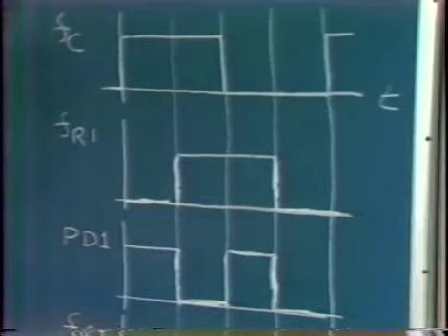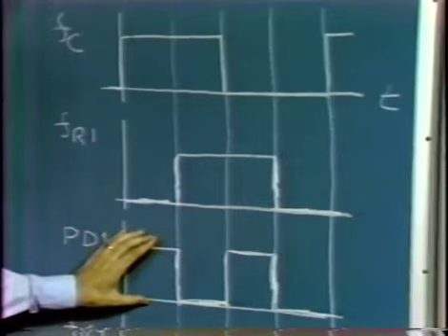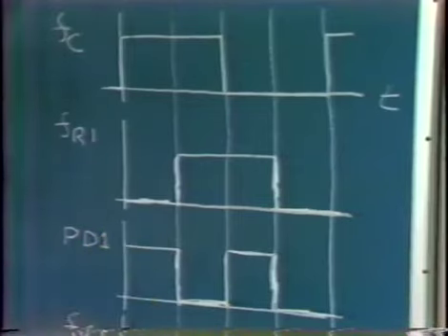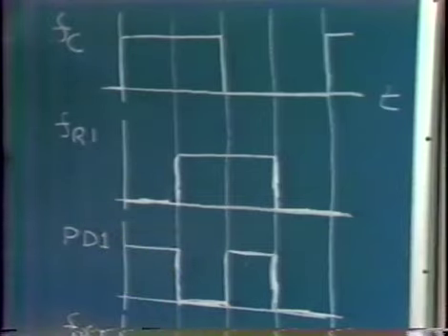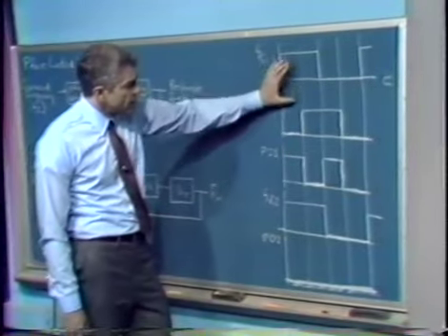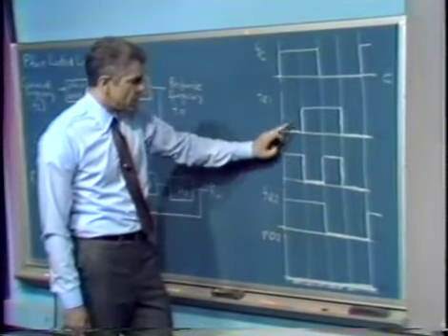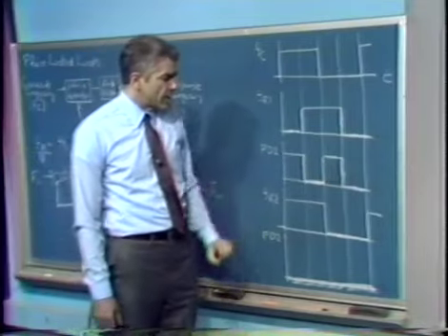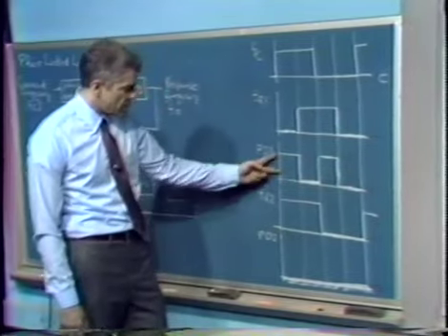And so to complete the phase detection process, we might standardize levels, not allow them the ambiguity associated with normal digital levels. We'd go through some sort of an analog switch so that we got standard levels coming out of our exclusive OR gate, and then go through a low-pass filter that extracted the average value of the output from the exclusive OR gate. In this particular case, where we have a 90-degree relative phase shift between the command signal and the response of the system, the average value of the signal out of the exclusive OR gate would be simply 1/2 of its maximum value, since it spends half its time in the high and half its time in the low state.